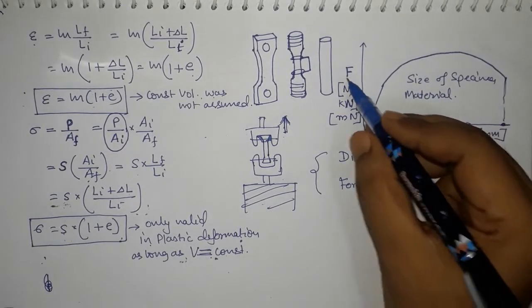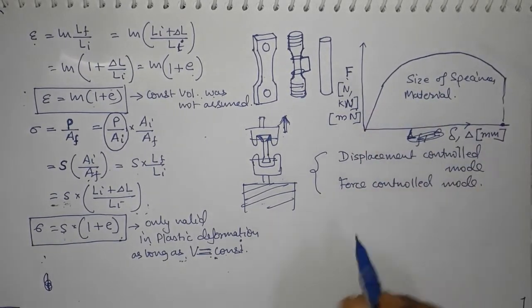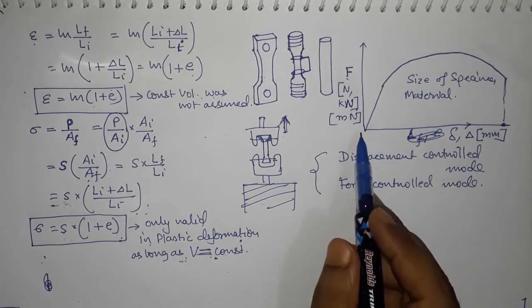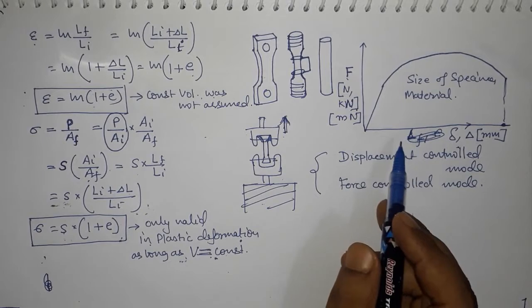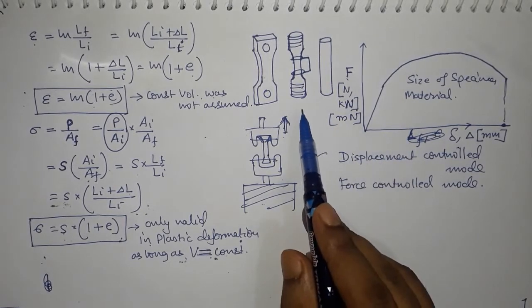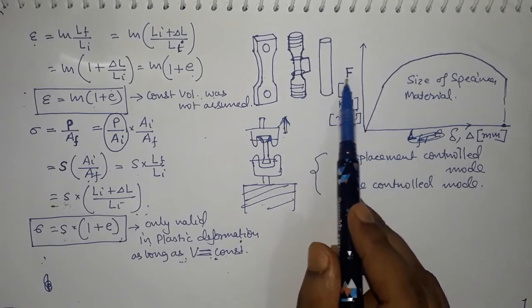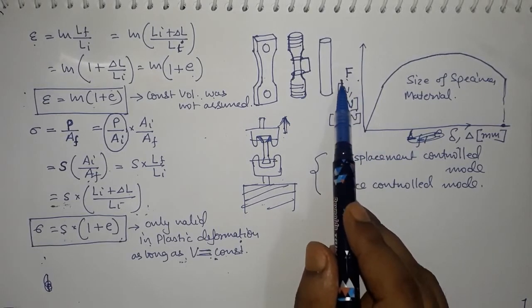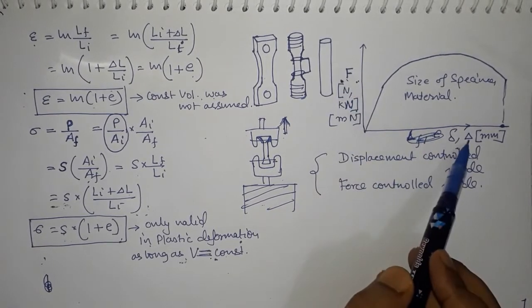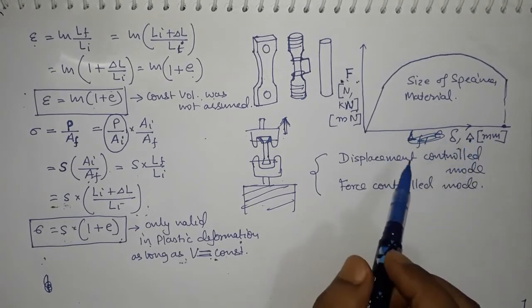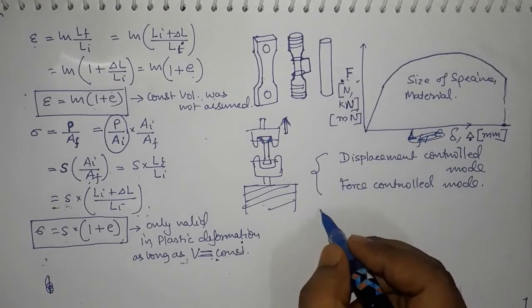So now from force and displacement you can calculate, and this can be done also digitally, either by the machine itself or the software in the machine, or you can do it by just exporting the data from the machine. So you can get from the machine the force and displacement values and the post processing, the further analysis, you can do by yourself.